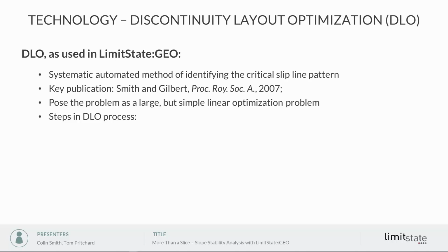And the answer is yes, we can use what's known as discontinuity layout optimization to take that limit analysis technique to its limit, if you like. So this is a systematic, automated method of identifying the critical slipline pattern using limit analysis, published back in 2007 in the Proceedings of the Royal Society, and essentially poses a problem as a large but simple linear optimization problem.